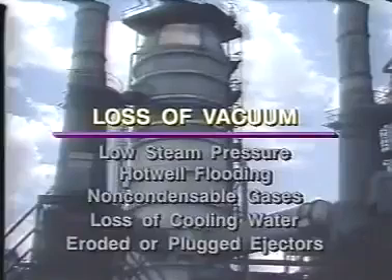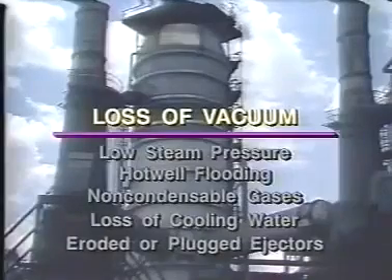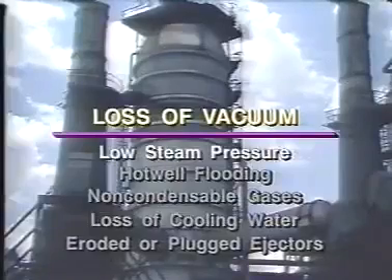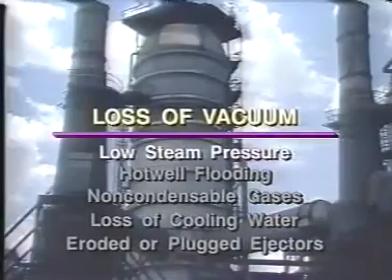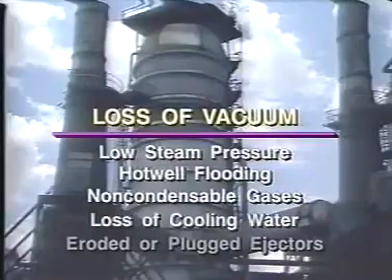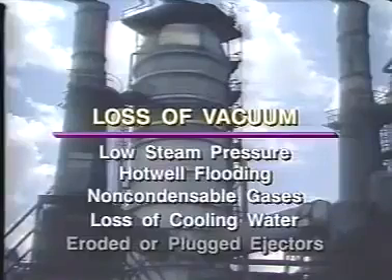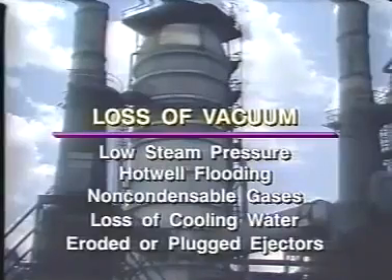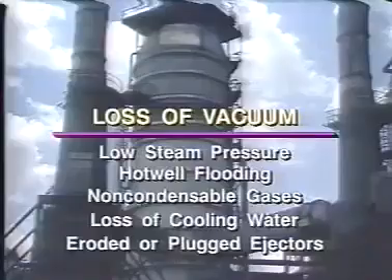A loss of vacuum in a vacuum distillation column is usually caused by one of the following problems: improper steam pressure to ejectors, hot well flooding, the presence of too many non-condensable gases, loss of cooling water to condensers, or erosion or blockage of steam ejectors.